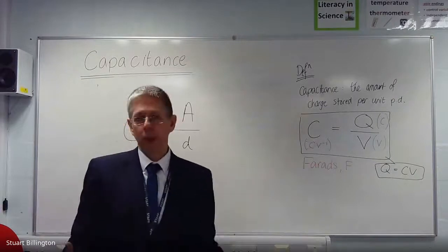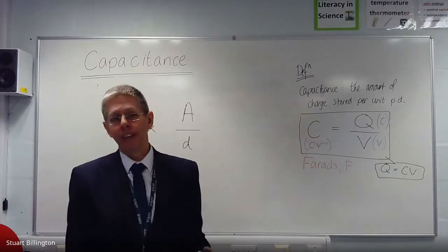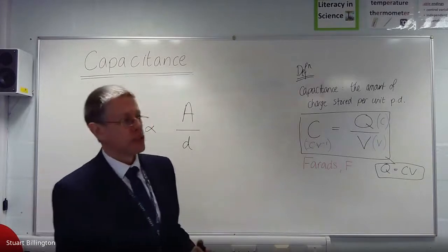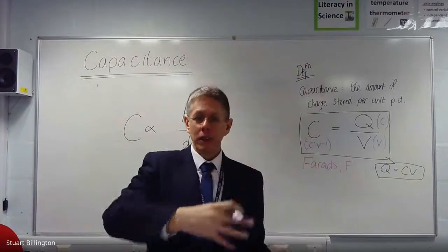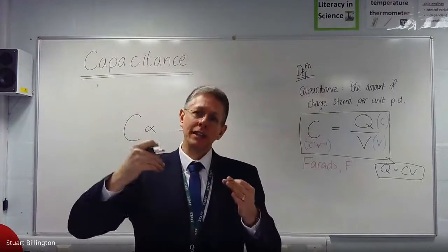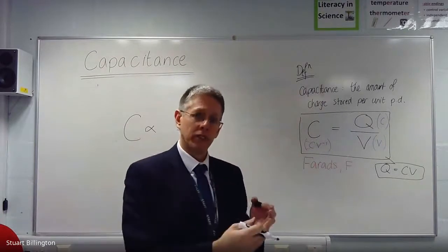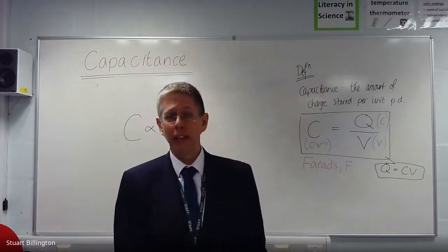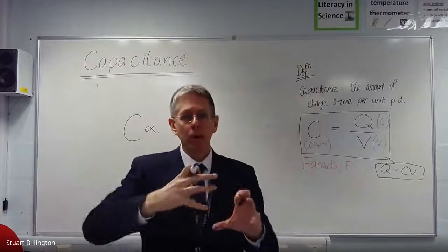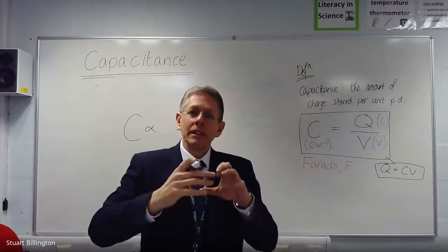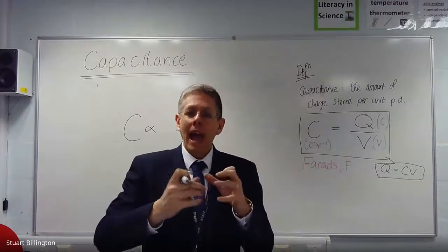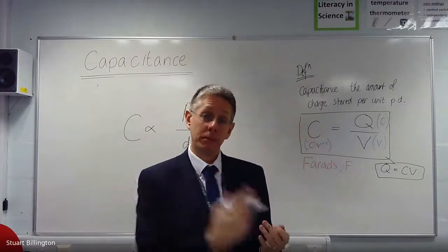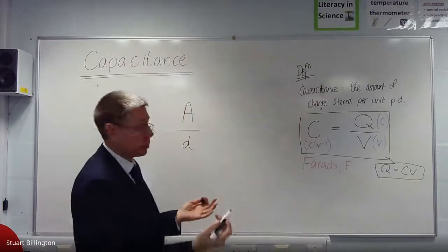And then also locked up in here, we need to have something about the dielectric. Its insulating properties, basically, how good it is at preventing the electrons flowing. But it's not really resistance as in V equals IR, because that's a definition of resistance when there is a current flowing. But the dielectric's entire job is to prevent a current flowing. So it's not quite as simple as resistance, but it's that kind of concept: how insulating is it, how good is it at preventing electrons from flowing through it at all.